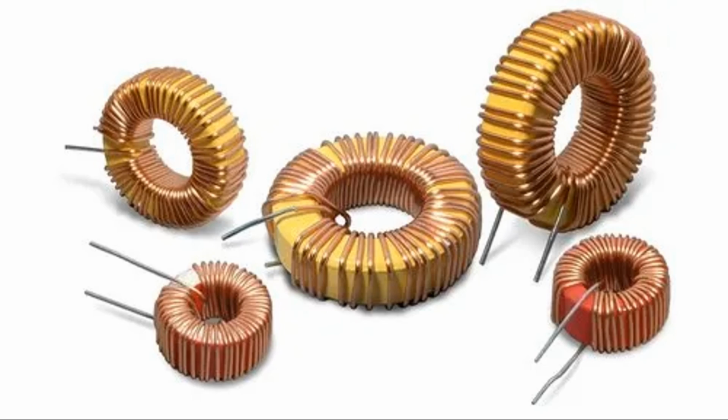Activation and control. Rotary solenoids are typically activated by supplying an appropriate current to the coil. The coil is energized to generate the necessary magnetic field for rotation. The duration, intensity, and polarity of the current can be controlled to achieve precise and controlled rotary motion.